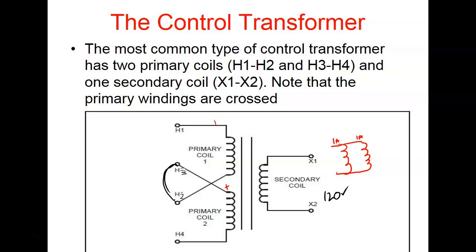And that's the second lab we'll do. We're not going to hook up a circuit. We're going to hook up our transformer. And once we hook up our transformer, it's going to stay hooked up the whole semester long. So we'll end up using a divide by 2. We're taking 240, which is not exactly 240, we're getting 208, but it's good enough. We're taking it and dividing it by 2 because all our components are rated at 120 volts.